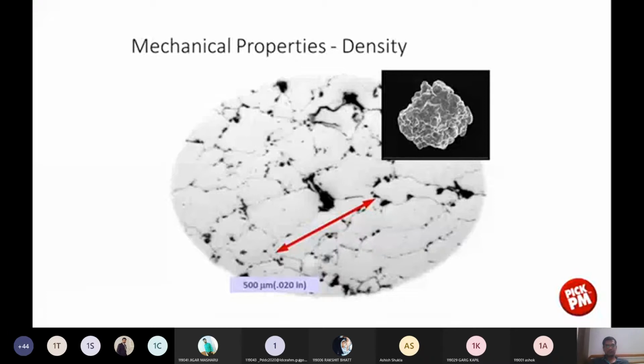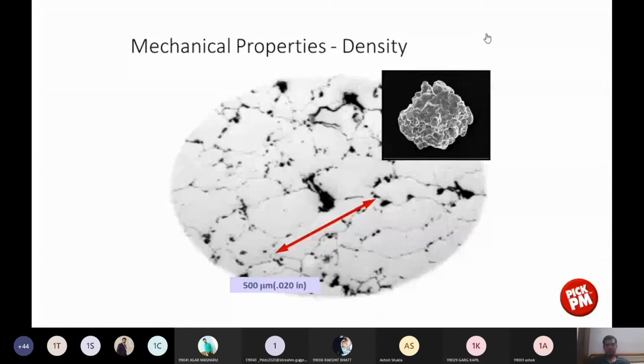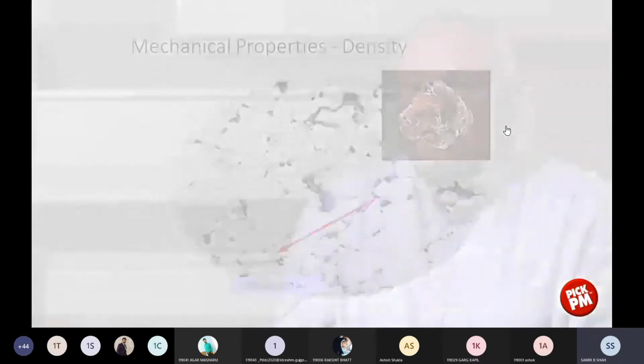In this graphic, you can see a powder particle, and you can see the deformation that occurs in compaction. So what's really happening in the compacting process? As we increase density, we're decreasing porosity. And what we see here is an increase in the area of contact between powder particles due to particle deformation in compaction.